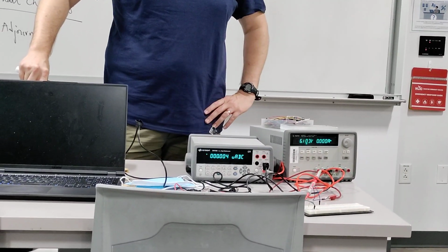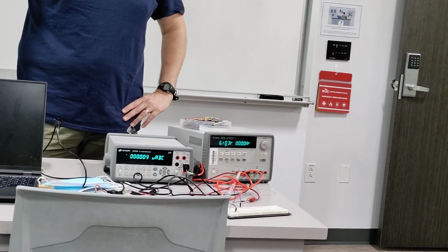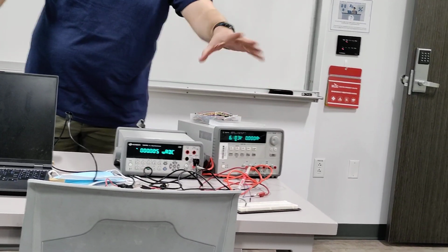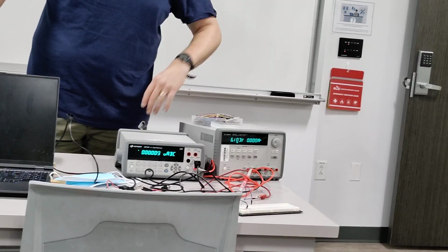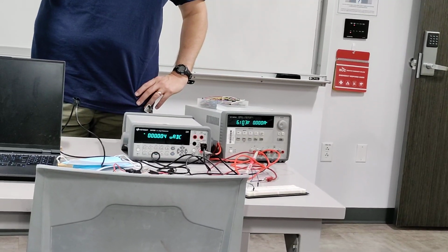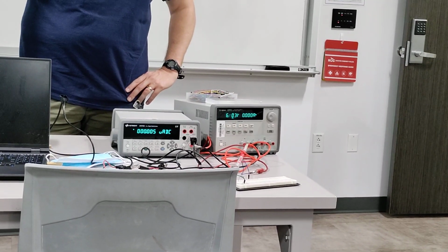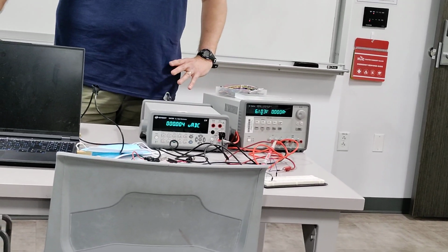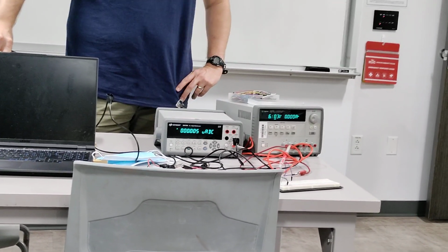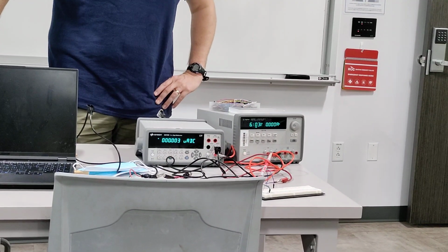Is there any safety recommendation when we're using the breadboard? Is there anything we should not do to fry the breadboard? Current limits on the DC power supply. Most important thing: 100 milliamps will not fry the board. Once we get to lab 5, the op amp lab, those are pretty sensitive. Those burn. You can burn yourself with an op amp when it goes, and it does happen. I really hope it doesn't in this lab, because they're the only thing worth more than a nickel, and they're the thing that everyone breaks.